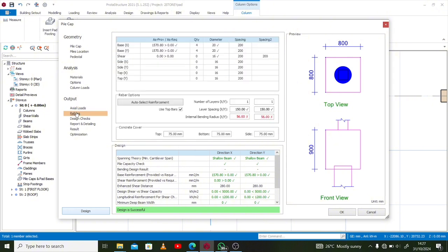All right, so the next one, rebars. Now in the design, the result of design says we are applying Y20 reinforcement at 200 mm spacing. You can also edit this if you want. Okay, so by doing this you can edit what you have. Once you edit it, it actually affects the overall design. But once you come here and you want to auto select reinforcement, once you do it, you see that it changed what you have there. So it's either you edit yourself or you allow the software to select the reinforcement for you. Okay, and that's that on rebars.